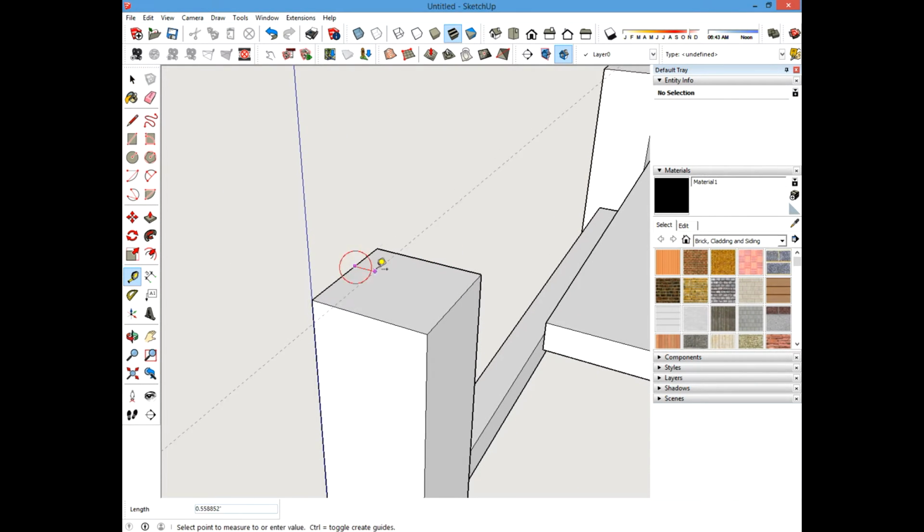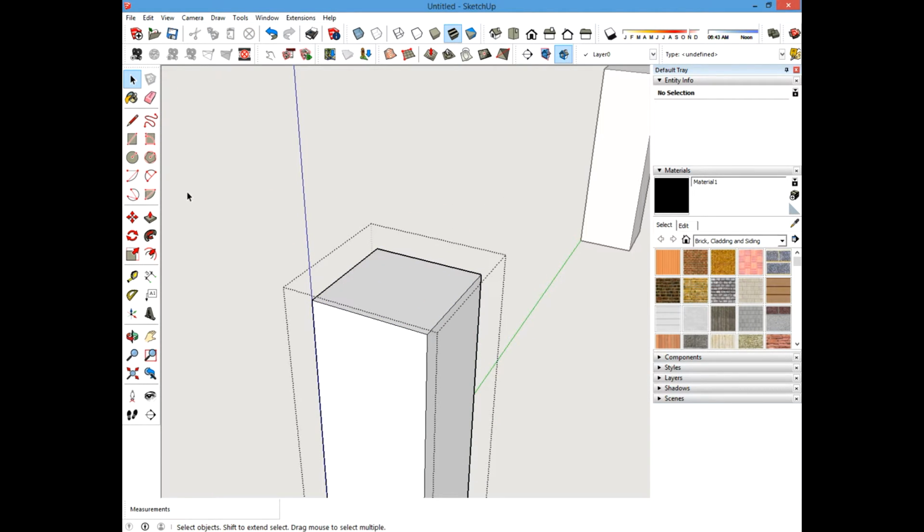So what we can do is, again, add holes here. We can snap to the midpoints here. Add a hole. Oh, I'm making the same mistake. We got to go into the component. There we go. So double click on that, and let's start over. Snap to the midpoint.